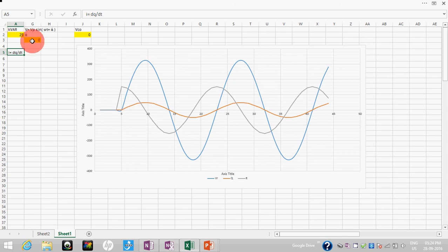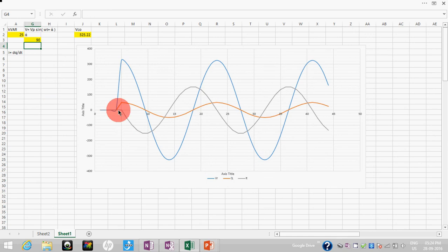Now suppose what happens if we start at the peak of the voltage. As we said, the initial voltage on the capacitor is 0, and we apply the voltage at peak level, that is, at maximum voltage level. Suppose the switch is closed at this time. If you see this line, it is a vertical line, so the slope is a maximum at this particular point on the graph. As we discussed, Q follows V, so the same sharp slope is seen in this Q waveform.